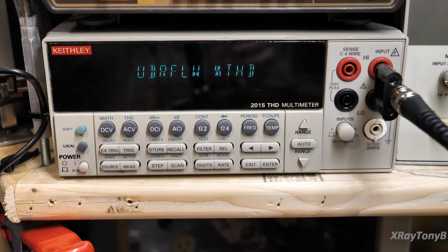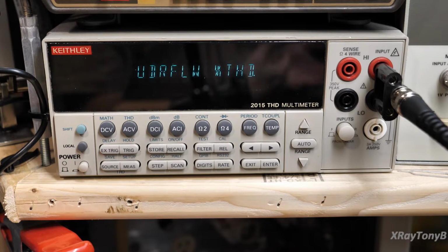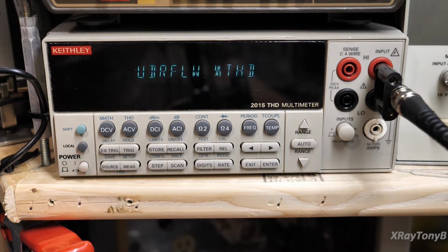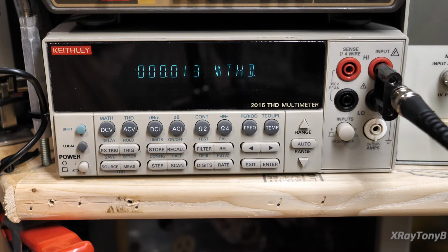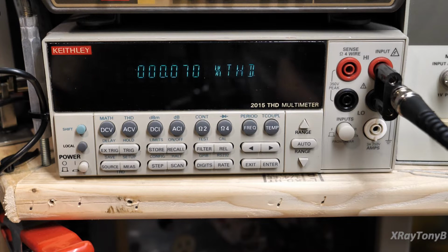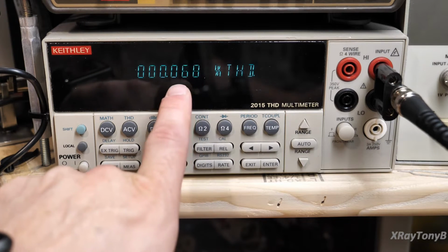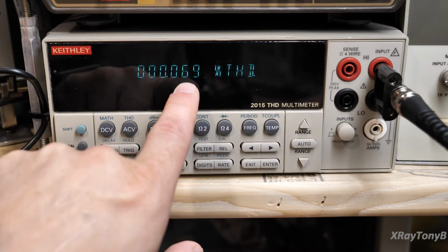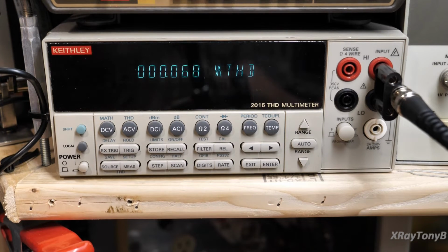Just for the fun of it, I switched the distortion meter to the other channel. So now instead of looking at, I believe it was the left channel, we're now looking at the right channel. And I found something pretty interesting here. So of course we go up to our 10 watts again, or our 14 watts, whatever that is. And you can see the THD is even lower. But curiously, when I get to that 60 some watts, I'm actually right now at 60 watts per channel, look at that. That's half what the other channel displayed at this level.